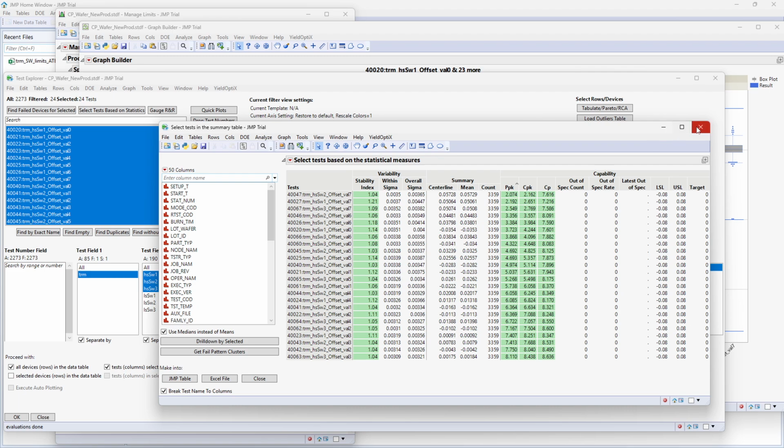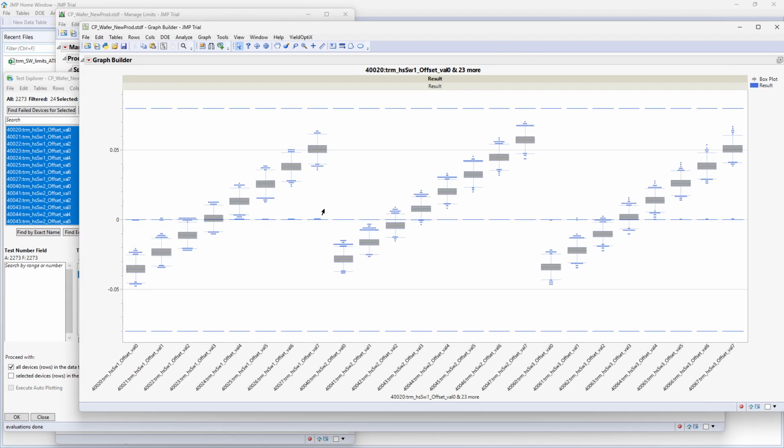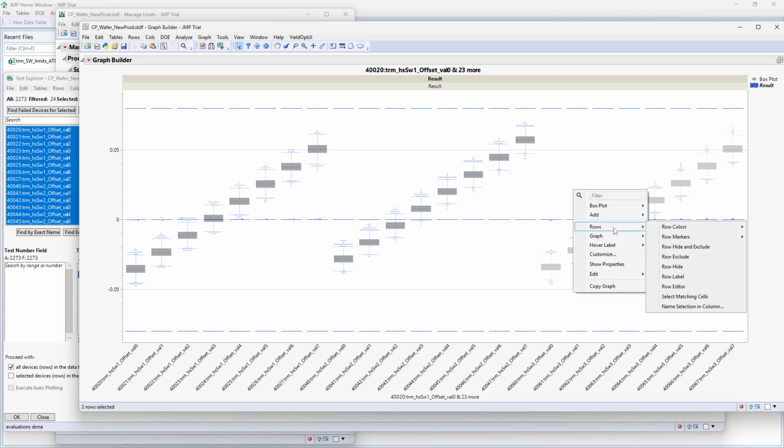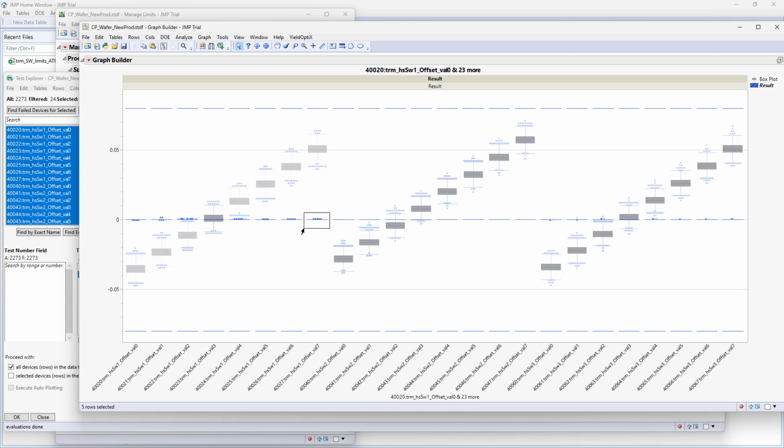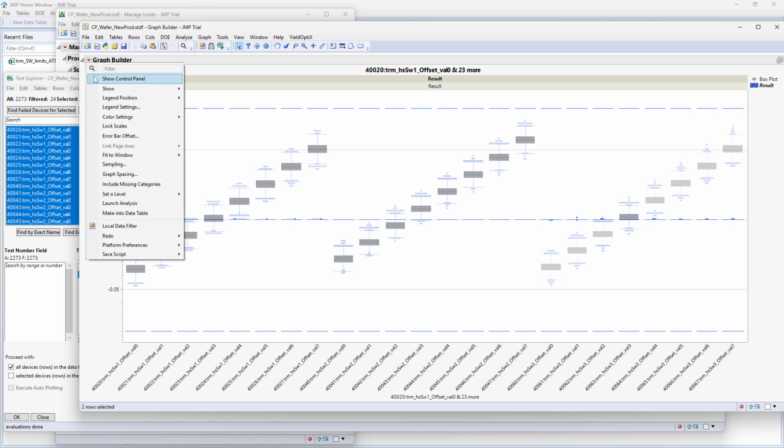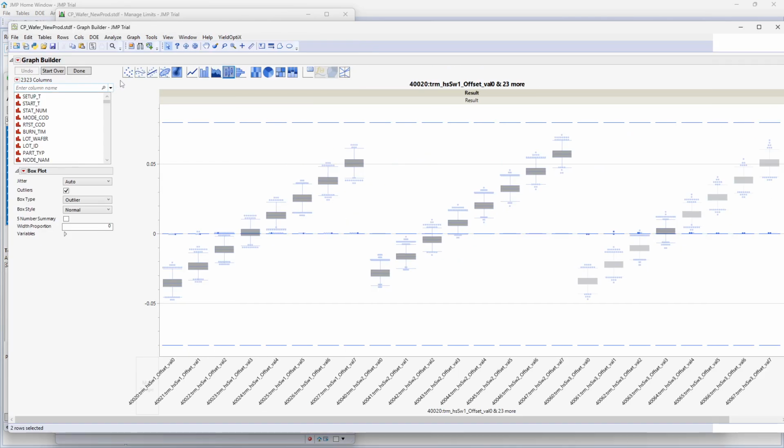However, upon reviewing the chart, it becomes noticeable that some tested parts clearly stand apart from the main distribution, showing a steady readout around 0 across multiple trim codes. Unfortunately, the currently applied limit set accepts these questionable results as passing. These results appear highly suspicious, and due to potential reliability and quality risks, such outliers should ideally be screened out.